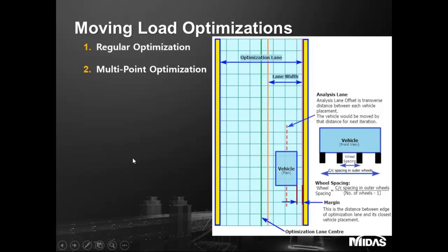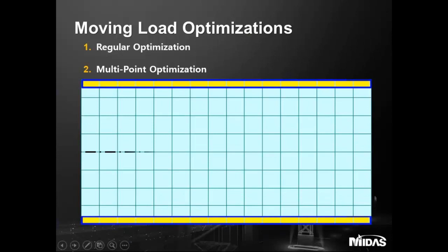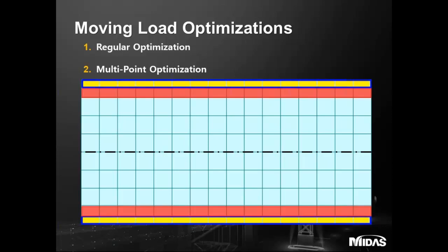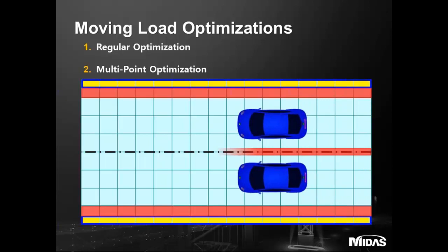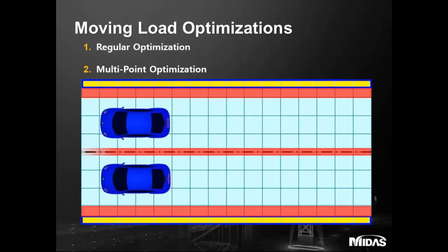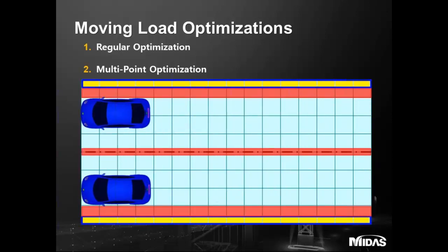So how that would work is, say again the same bridge, the center line of my carriageway, and this red zone is the edge part where the vehicle is not allowed. If I say my carriageway is to carry 2 vehicles, then with just that input, the software will check the entire bridge for any vehicle position that could be encountered. Okay, so all of this could be covered with just single lane definition.